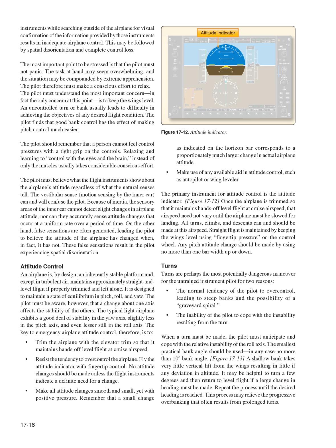The most important point to be stressed is that the pilot must not panic. The task at hand may seem overwhelming, and the situation may be compounded by extreme apprehension. The pilot therefore must make a conscious effort to relax. The pilot must understand the most important concern, in fact the only concern at this point, is to keep the wings level.